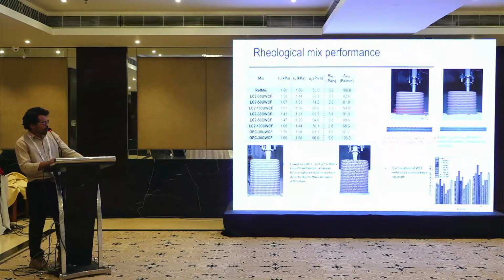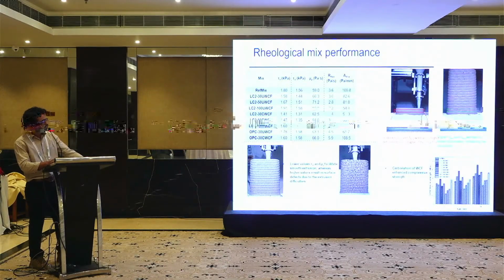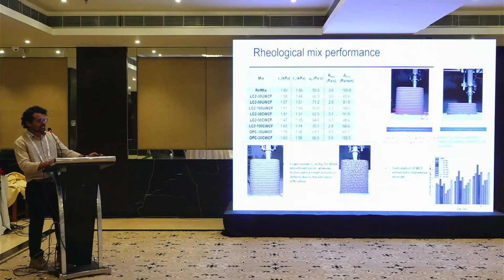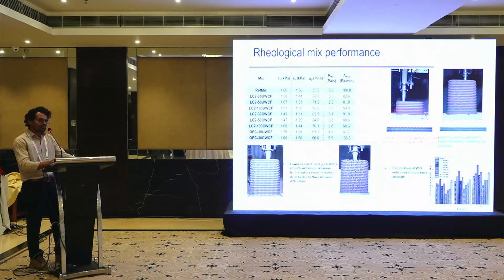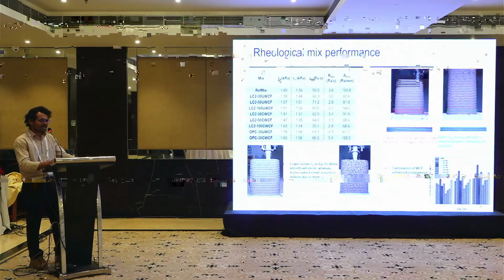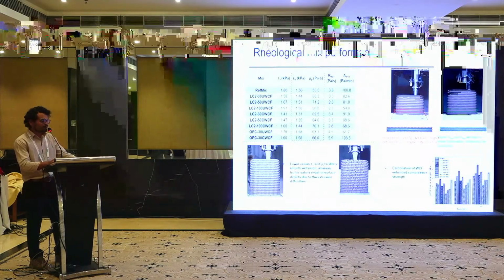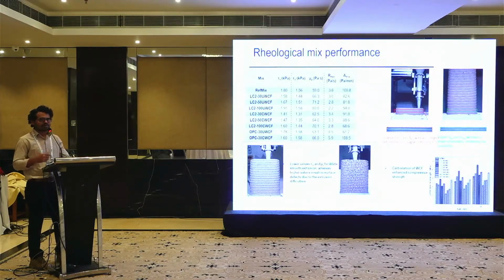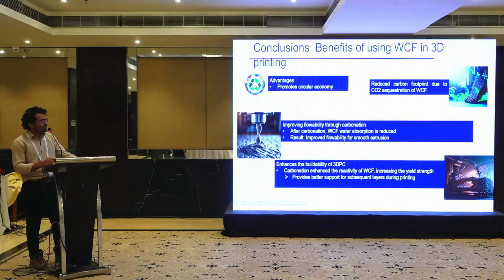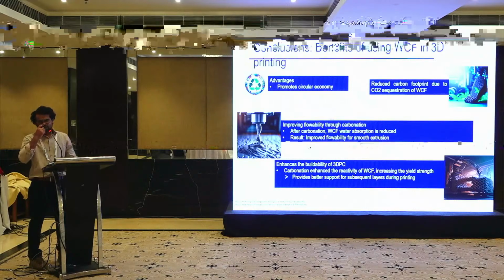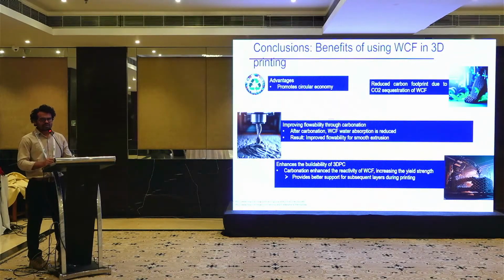So these are a few more properties that are very important for printing: static yield stress, dynamic yield stress, thixotropy and structuration. With carbonation, all these properties increase the reactivity of the material, and together it increases the buildability of the mixes. The advantage of utilizing waste concrete fines is that it promotes a circular economy, and together with carbonation it can sequester CO2. The formation of reactive products during carbonation, calcium carbonate and alumina silica gel, will result in a higher structuration rate, which ultimately contributes to higher buildability.